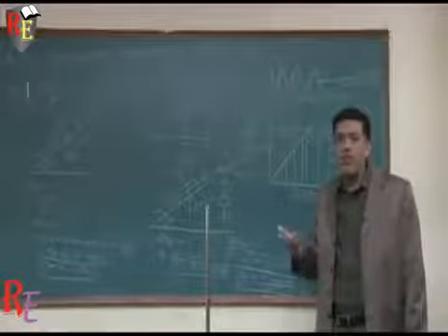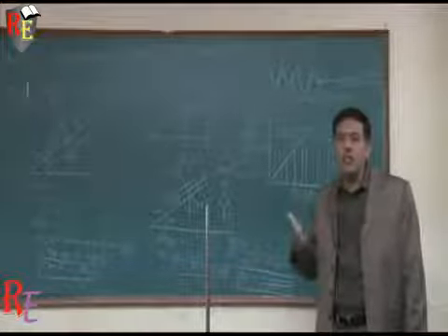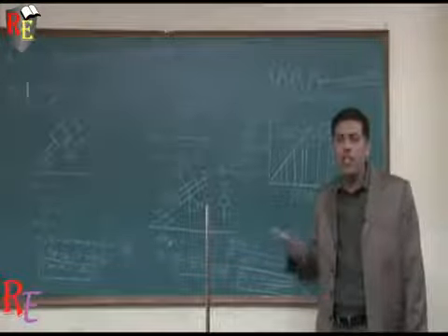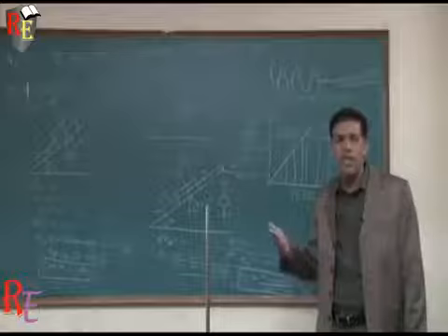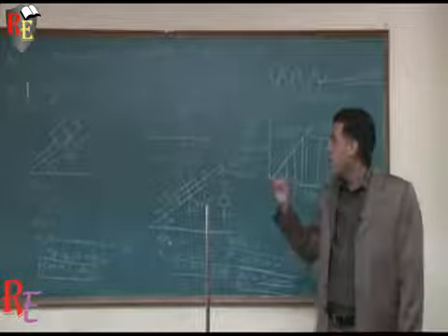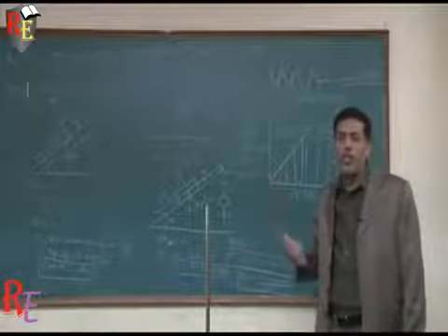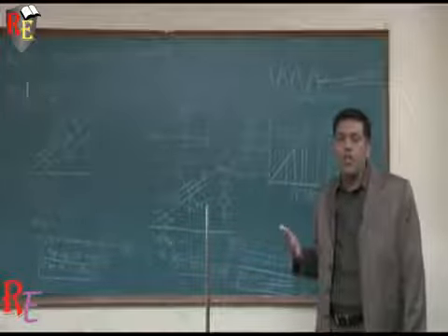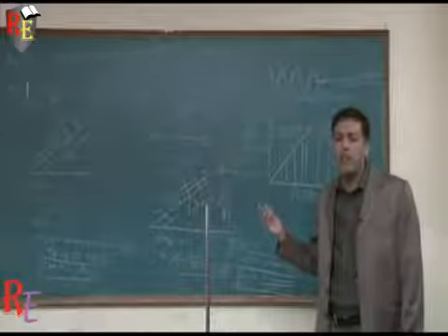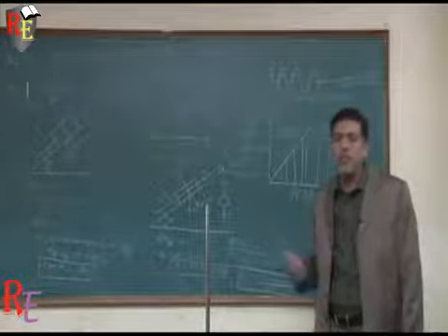All the frictional drives or mechanical drives are possible due to friction, whether it is the frictional clutch or the brakes, etc. If we determine the coefficient of static friction, it helps us in the judicious selection of the frictional material for various applications.